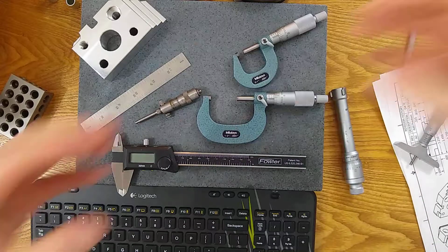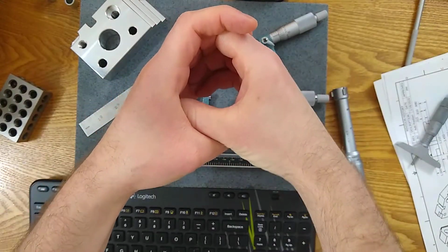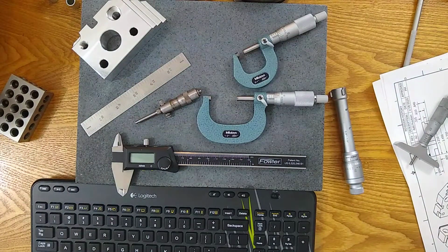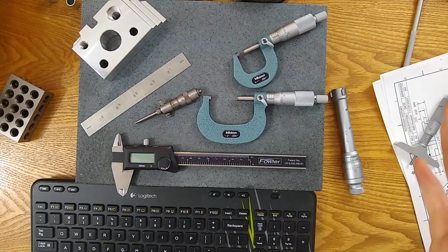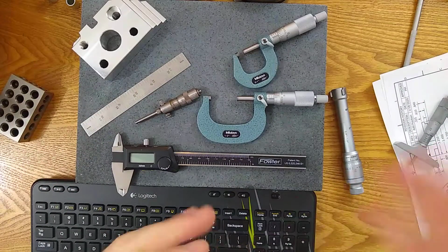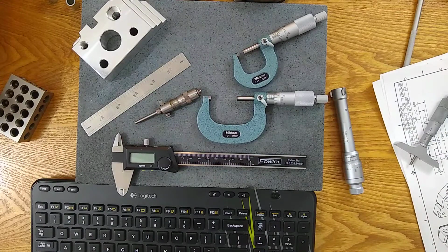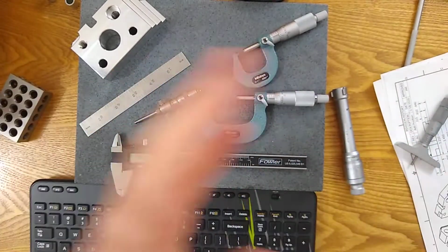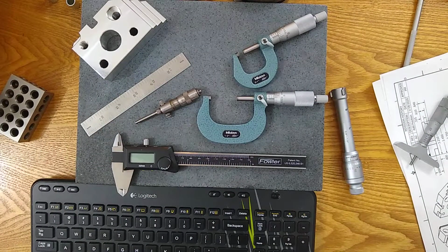And it will take into effect how large you're measuring. So measuring something small on a CMM will give you a better accuracy number than measuring something large. And sometimes that difference can be a problem for your uncertainty ratios, or sorry, for your accuracies. Those accuracies might end up bigger than the tolerance zone or close to the tolerance zone. But you can still calculate an uncertainty ratio to give you a ballpark for choosing if you're going to use a CMM or not.